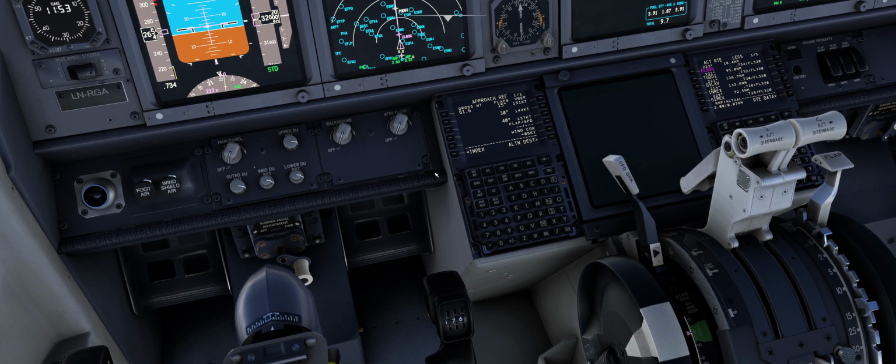This will be our gross weight for landing, so we'll put flaps 30 as we have 20 knots of wind condition and plus 10 knots as the VREF additive. In this case, our approach speed will be 154.